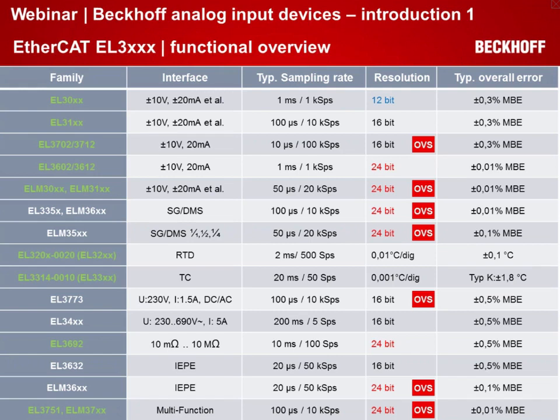On these terminals you can measure voltage and current in 3 phases at the same time. These terminals are very good to use when you want to make a clear detection of the zero crossing, or to measure any values of power that is used by your machine.